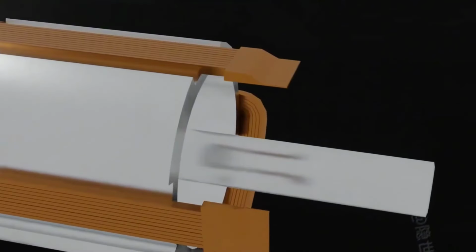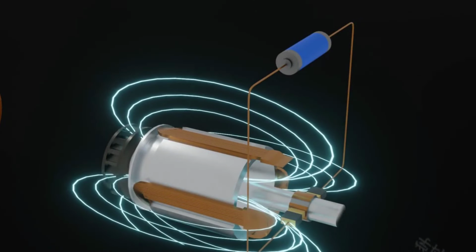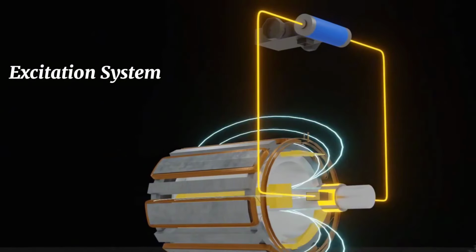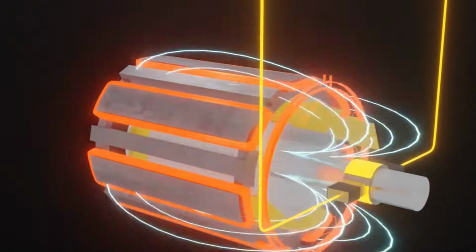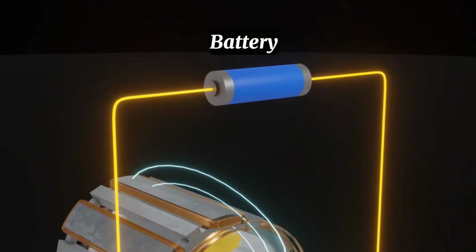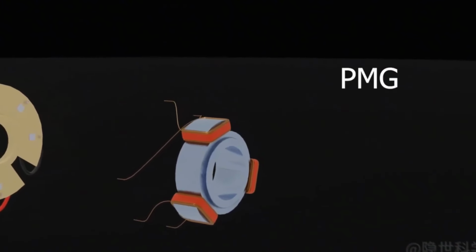This is called an excitation system, i.e., a system that provides an initial current to generate a rotor magnetic field. There are two types of excitation systems themselves: external type and self-generated type. In the external type, the current comes from an external source such as a battery. This type is usually built into the alternator on the car, while the self-generated type uses a component called PMG, permanent magnet generator.